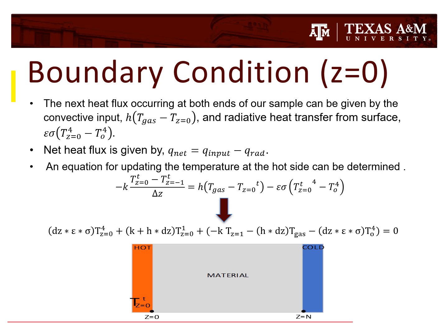Using Fourier's law, we can then set our net heat flux equation and solve into the form of a fourth degree polynomial. We will then be able to, just like previously, iteratively solve this using MATLAB, which will help us model our thermal response. This gives us an equation that updates the temperature at the hot side over time.